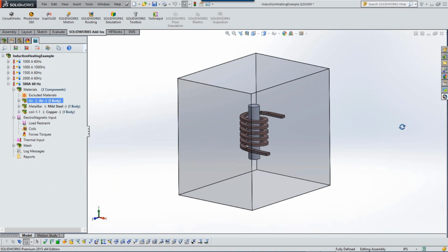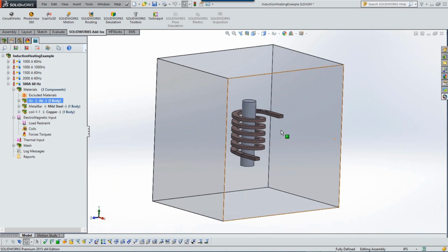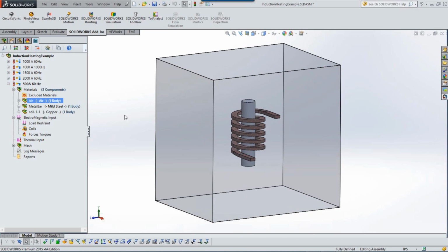Okay. Now, as you gentlemen and ladies know, the electromagnetic field not just exists in the coil, it does not just exist in the ferromagnetic substance, but it exists in the atmosphere all around us. Okay, and it's extremely critical to capture this magnetic field that's there in the air. So we do that by creating another geometry called air. Okay, and we assign that a material which is of air.